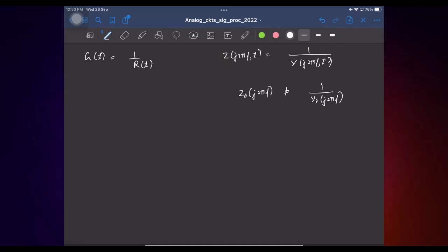And this is all happening because we have been sticking to the LTI notion of impedance, where we are just looking at the current and voltage at the same frequency. But in LPTV, we know we don't only have a frequency at f. What all frequency components do we have? Yeah, f plus k fs. So we'll now see a more generalized form of an impedance, where you take the currents and voltages at each of these frequencies and take into account the frequency translations.